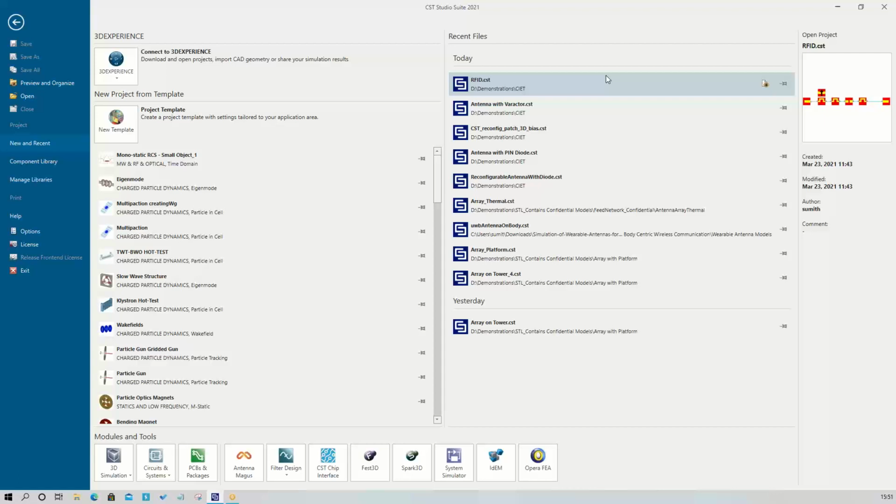That is the reason I will tell you that in 5G, we are using only active antennas. The active antenna is equipped with a phase shifter matrix. This phase shifter will mostly be provided like a default matrix, and from time to time it will give us a switching. We provide the necessary time pass, and according to that, it will switch to different directions. So what it does is scan each angle, each direction. Whatever the intended radiation area is, it will scan all of it, maybe minus 60 to plus 60, minus 45 to plus 45 in azimuth and elevation.